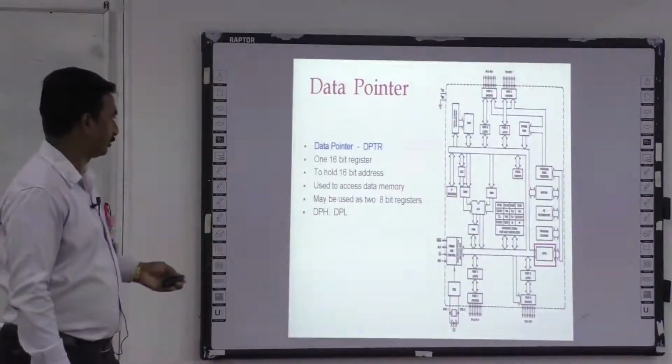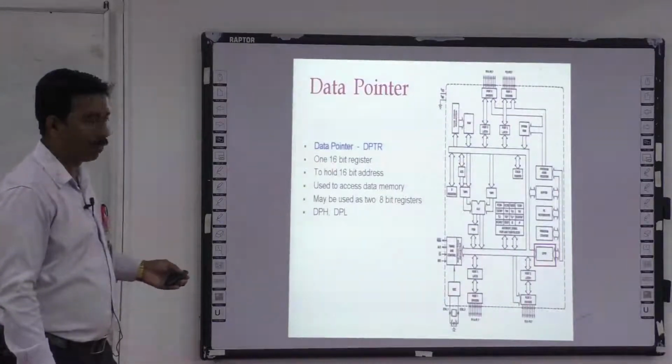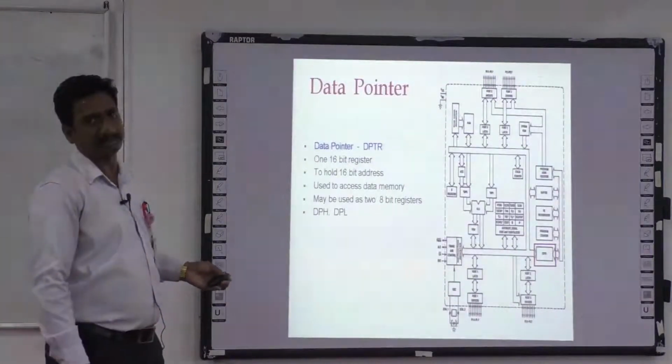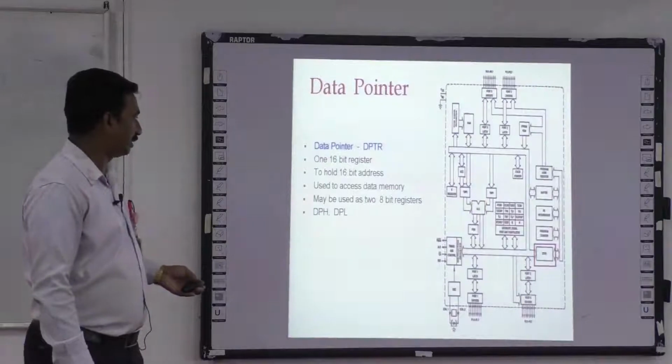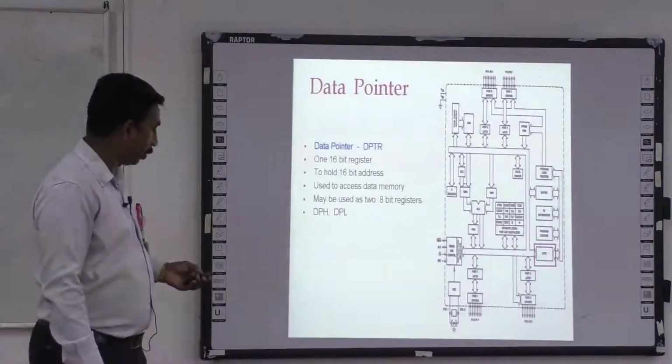devices or instruments. And maybe use 2 8-bit registers. If you don't want to use 16-bit, we can use it as 2 8-bits. One is DPH, another one is DPL. Data pointer high and data pointer low.